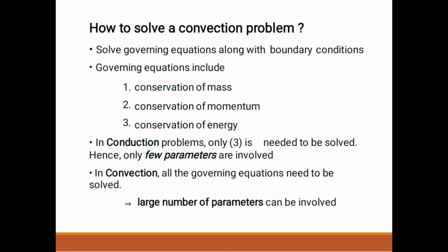How to solve a convection problem? Solve the governing equations along with boundary conditions: conservation of mass, conservation of momentum and conservation of energy. In conduction problems, we need to solve only the energy equation. In convection, all the governing equations need to be solved.